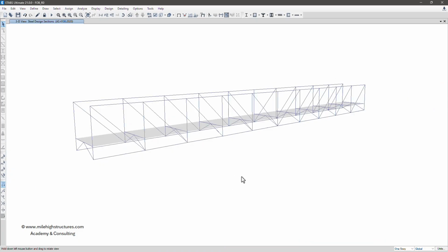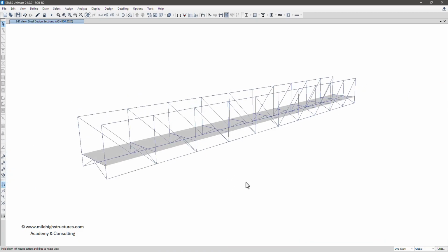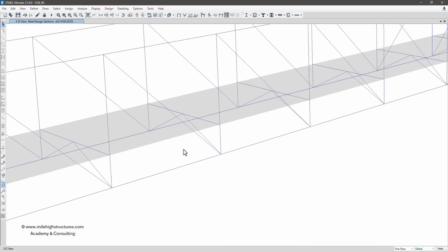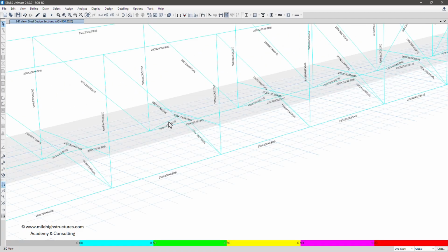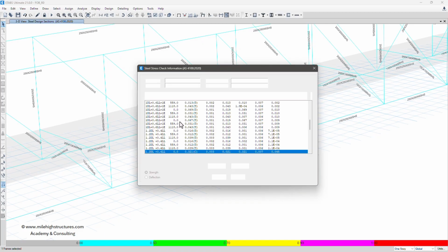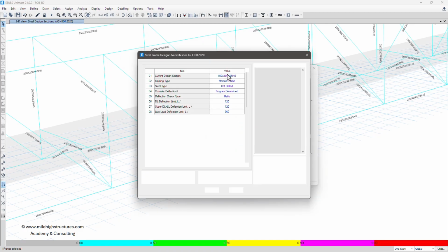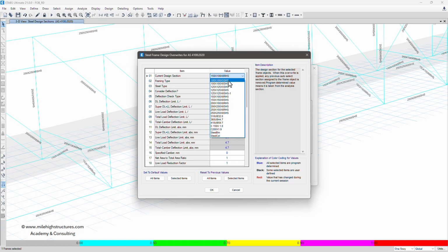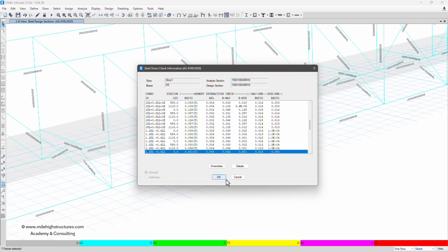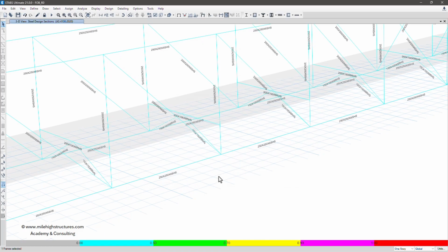So what we can do is that is a repeated cycle of permutation and combinations that we do need to continuously change. So let us say if we are first of all talking about this particular case, that is 150 by 100. So we can reduce the size of this member. So instead of 150 by 100, let us say we proceed with 100 by 100 by 5. So in that case, it is approximately 0.6.